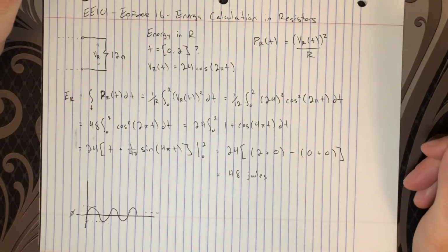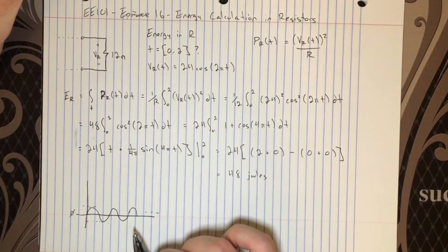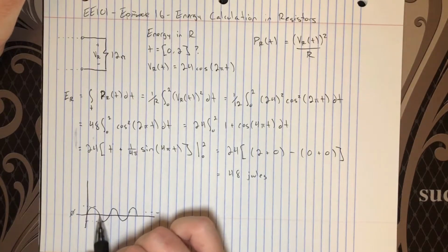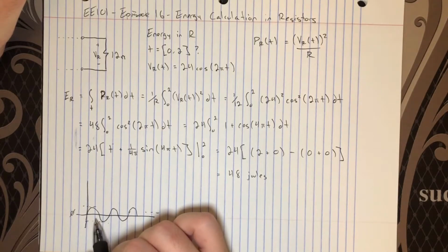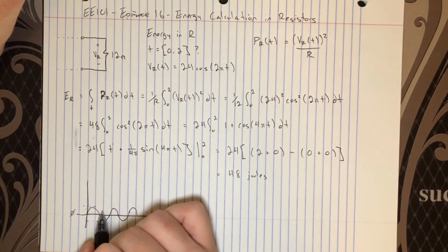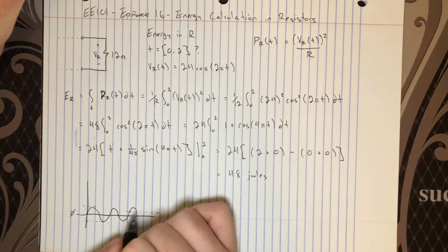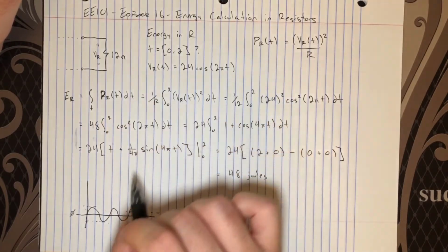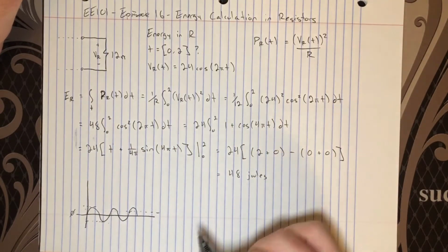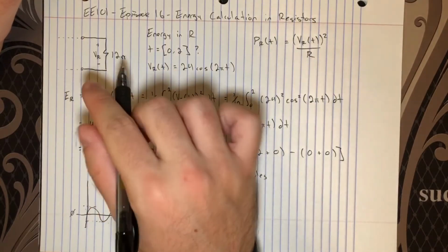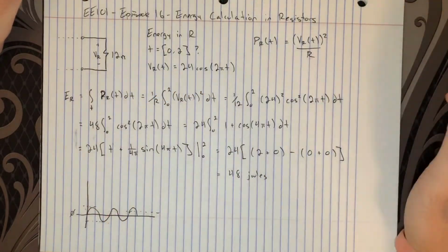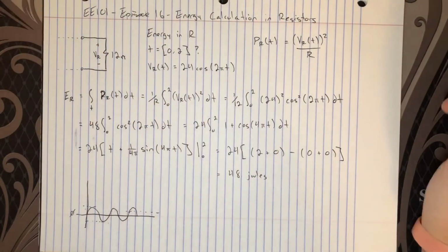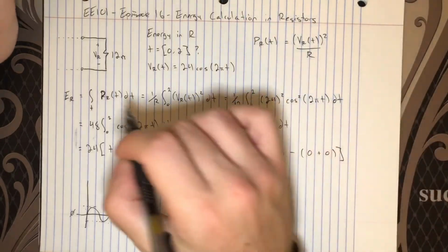So basically, RMS is a type of average that allows you to ignore the fact that the polarities are changing, and it essentially will convert the amplitude of this sinusoid into some equivalent, slightly smaller value that you could apply to this circuit, and essentially pretend that instead of a sinusoid here, you have some DC voltage. If that DC voltage were applied in the place of this sinusoid, you would deliver the same power over some averaged amount of time, or the same energy to this resistance.